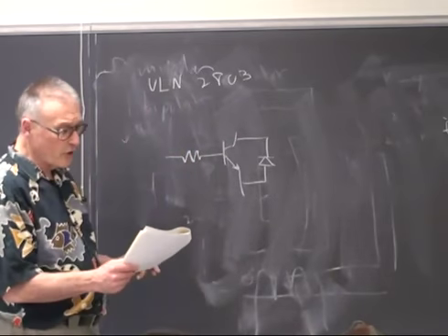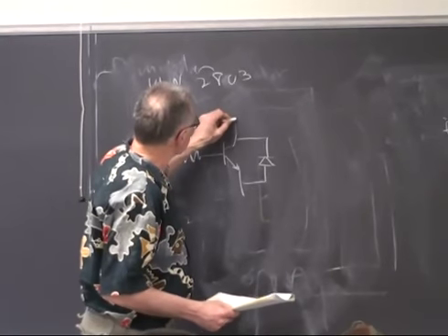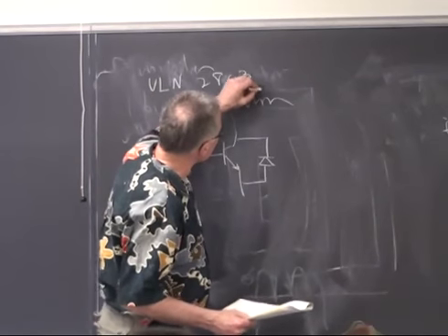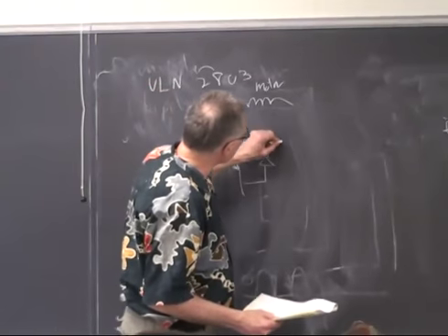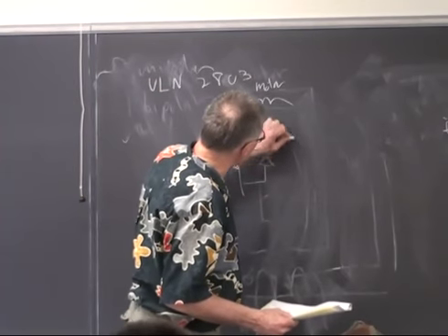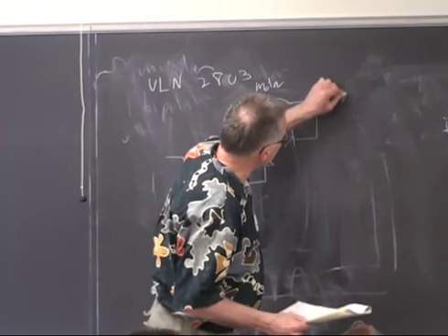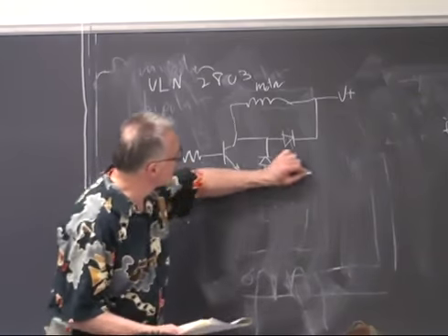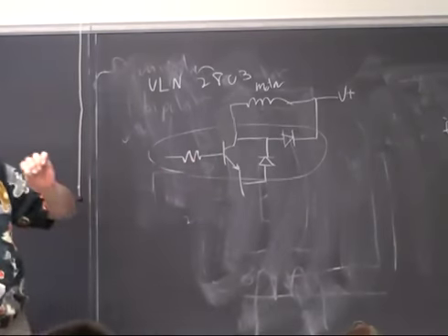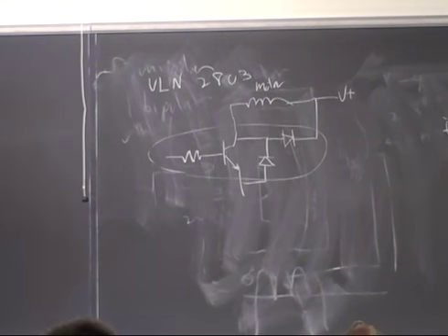In fact, it has 2 protection diodes, so that you go to the coil here. This is the motor coil. And internally is another protection diode, which then goes to V+. So there's 8 channels of this inside one integrated circuit. And they're each rated at about 500 milliamps with no heat sinking. Again, it runs pretty hot, but who cares?